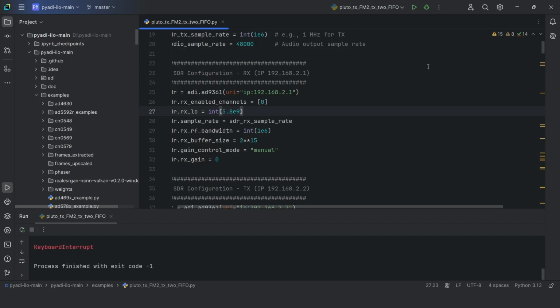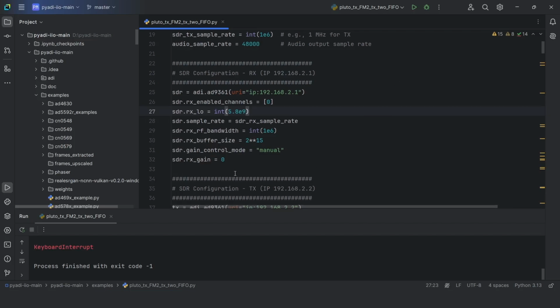One thing that is missing here is that we need to do frequency correction, because we need to see how we can first detect the frequency mismatch between the transmitter and receiver and then try to correct it. There are many ways that have been proposed to do that. For instance, frequency lock loops, which use the received spectrum, either by examining the symmetry of the spectrum or other methods, we can detect the frequency mismatch between the transmitter and receiver. For this FM, as I mentioned, we can use the DC information to have a good estimation of the mismatch between the TX and RX, and we are going to first detect that and correct it.